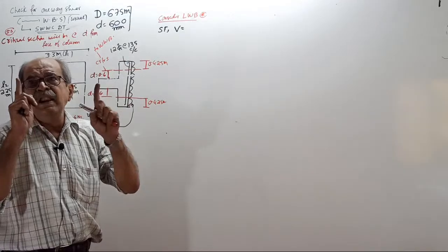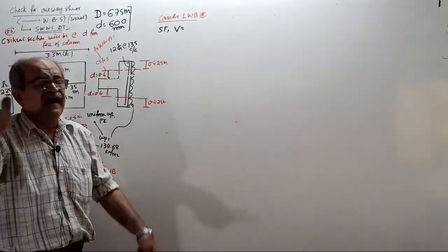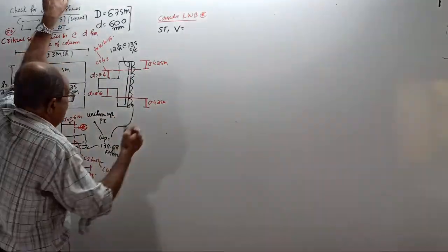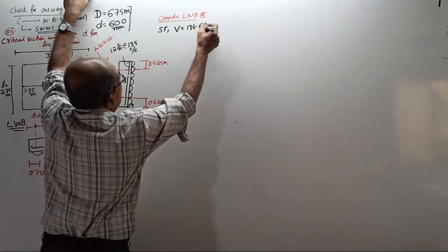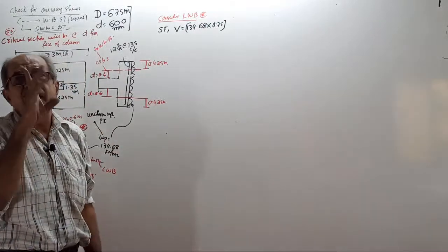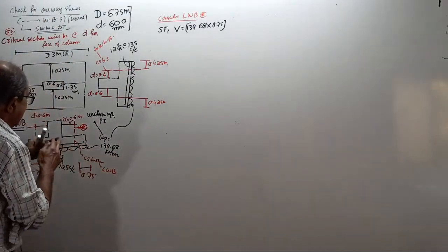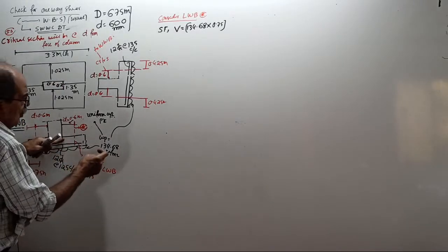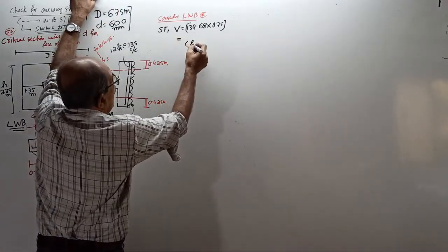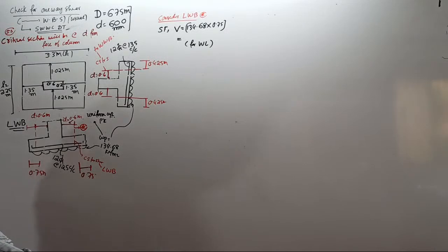Shear force is nothing but only load. So, 134.68 kilonewton per meter square means, I told class after class, it is not kN per meter square. It is kN per meter for 1 meter strip. So how much is it? 134.68 into 0.75. That is the total load. That's all. Suppose you want a bending moment here, that load into 0.75 by 2 will come. Like earlier, when we found bending moment at the face of the column, 134.68 into 1.35 into 1.35 by 2. Answer first. This is shear force for working load. Little fast you tell.